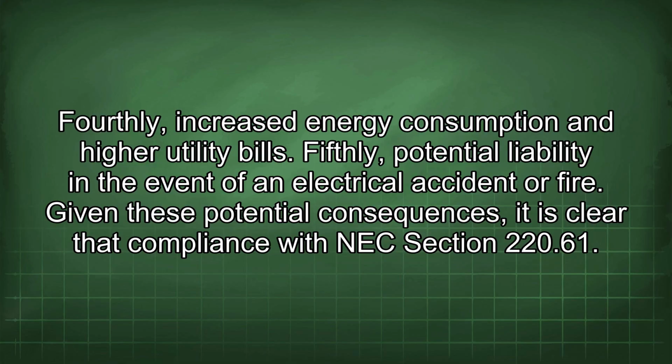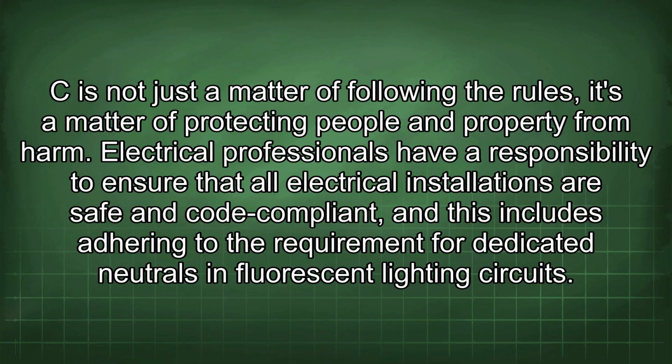Given these potential consequences, it is clear that compliance with NEC Section 220.61(C) is not just a matter of following the rules, it's a matter of protecting people and property from harm. Electrical professionals have a responsibility to ensure that all electrical installations are safe and code compliant, and this includes adhering to the requirement for dedicated neutrals in fluorescent lighting circuits.